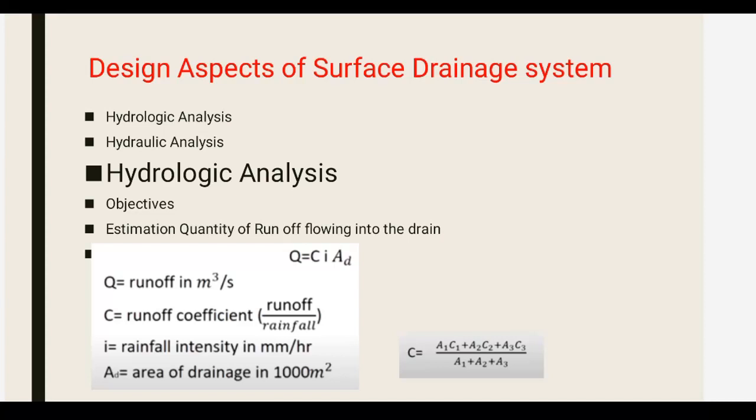To find the drainage area from where water is likely to flow in, and to determine the runoff and maximum rate of runoff for the area under consideration using any of the accepted approaches, or to estimate the peak quantity of runoff water reaching the component of the drainage system, that may be side drains or cross drainages, right? So these are the pre-feasibility studies required for hydraulic analysis.